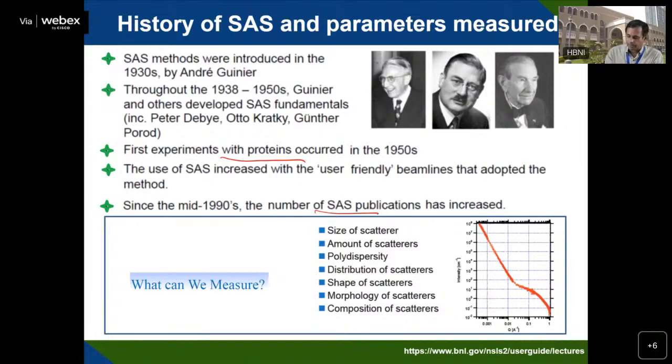So we can measure different parameters here. Here you can see what you will get from a spectrum: the intensity I, which you express as I(Q), versus Q, the wave vector. In X-ray diffraction you use 2 theta, but since theta is a very small angle here, we use Q, the wave vector that I discussed. From intensity versus Q, we get how the intensity varies with Q. Then we apply a Fourier transform to get the real-space data.